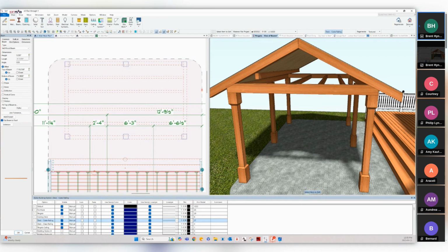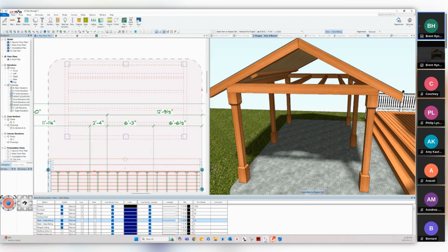I've drawn just a tongue and groove ceiling in here, at which point I can then edit that beam again and change it so that it's going ceiling plumb. So I didn't see a big movement there, but it moved up to it. Ceiling rake, so it tips it, and then ceiling flush, so it's going to flatten it out. Okay, and then once I've done that, I can repeat that change to the other beams and have them run through.